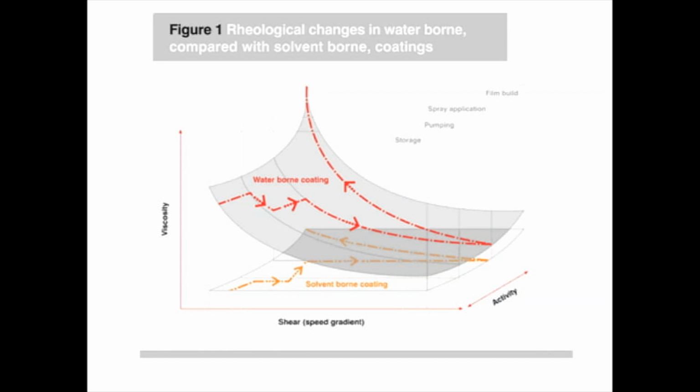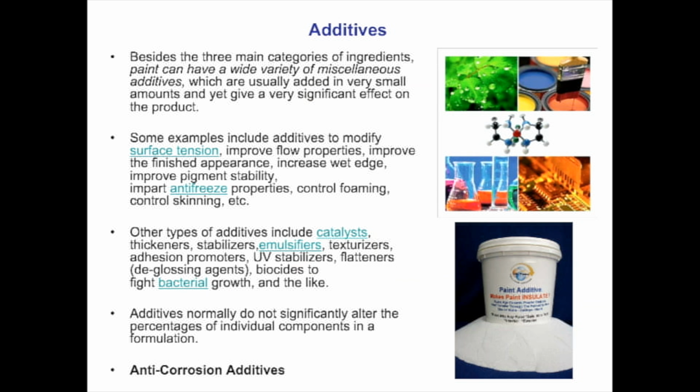Here you can see the rheology of paint, which is governed by time. So basically the viscosity increases as you evaporate the solvent from the film. On the other hand, the rheology is quite important when you're applying the coating in gravity-driven processes such as walls versus flat flooring or coating without the influence of gravity.